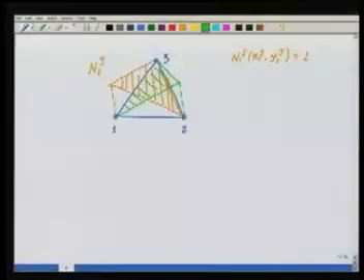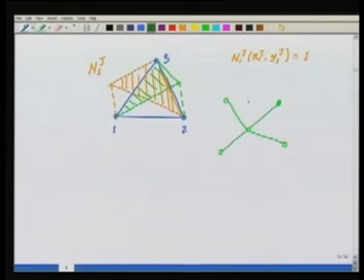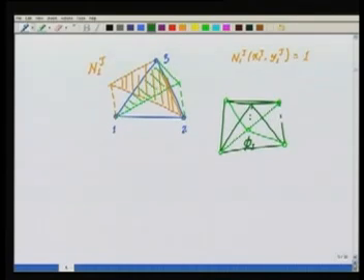And you can see that for the ith node, if I look at the shape function, it will correspond to a tent-like structure. That is, by piecing together all these shape functions, I get the global basis function phi I for the ith node of the mesh that we have, and this function vanishes on these black edges.